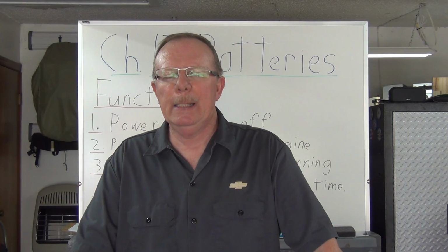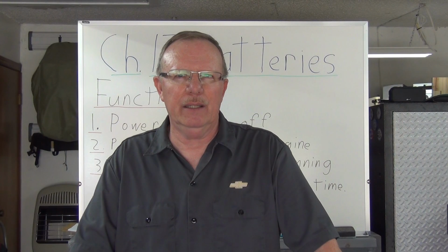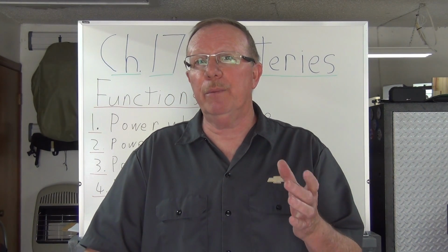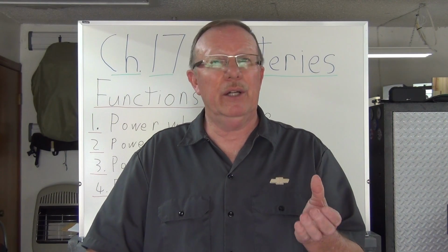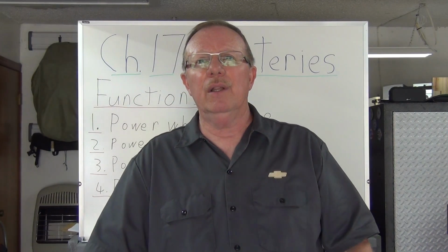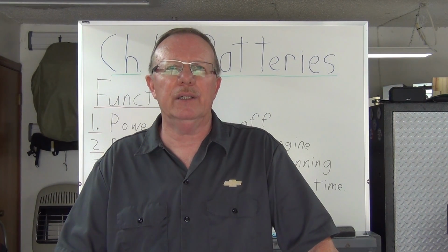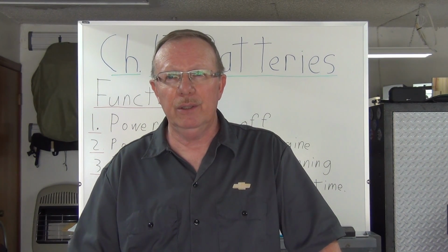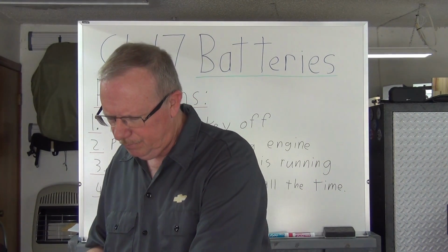Okay? Well, it determines the capacity of the battery. So the larger the physical size of the battery, the more plates there are in each cell. The larger the plates are in each cell, the better constructed they are, the better materials that are used, then the more capacity it has, all right? And we're going to look at ratings here in a little bit too. So it's not necessarily the size that determines the voltage, it's the number of cells that determines the voltage, and they're each 2.1 volts, okay? Very good. Glad you guys are staying with me here.